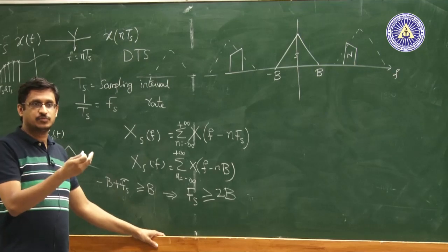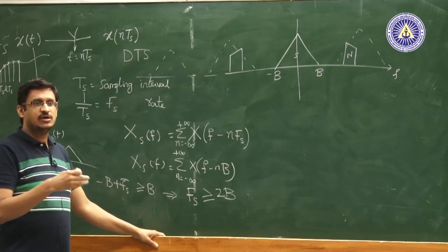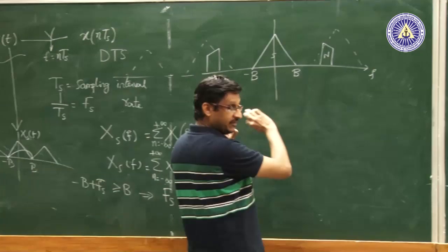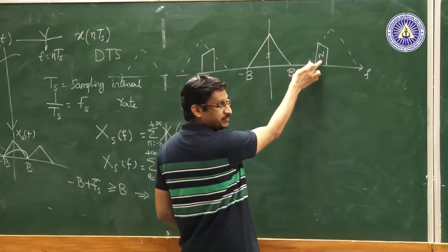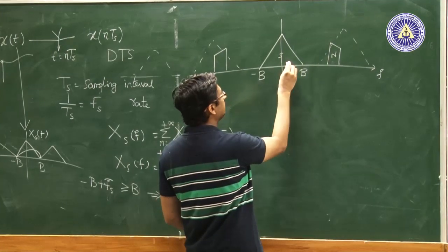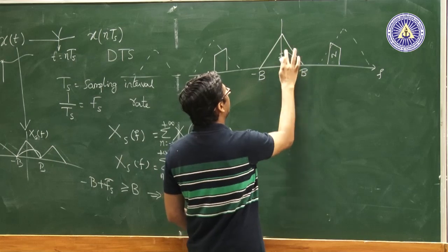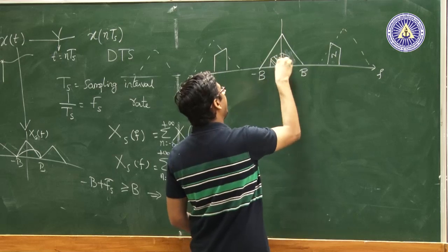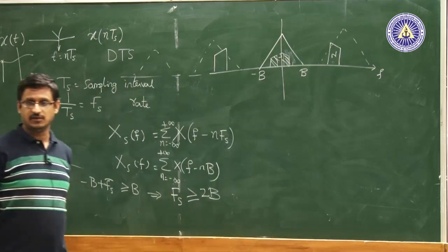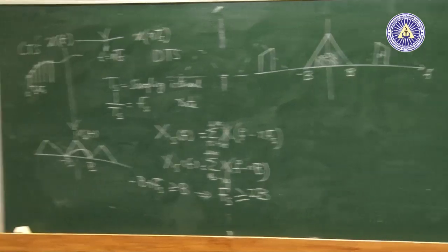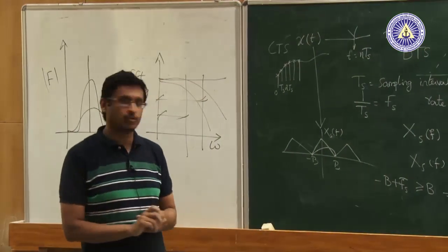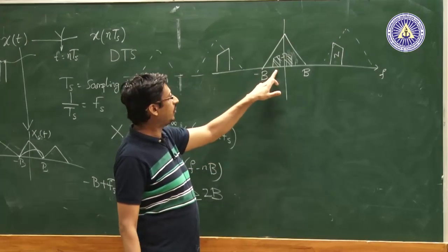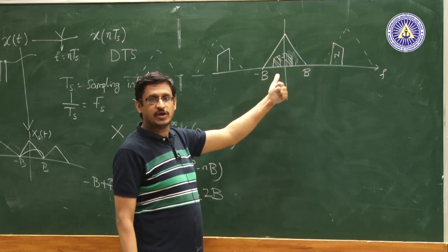because noise is also being sampled. You can't distinguish when you take a signal which also has noise in it, you can only isolate the signal and then sample it, right. You are sampling both. So, the effect of that in the frequency domain is that the noise spectrum also shifts, and this fellow will shift and usually will fall right into this one and then add noise into the signal band. If you had used a continuous time Fourier transform, you could have distinguished signal and noise. The sampled signal will have a Fourier transform in which, in the band of interest, you have the noise spectrum also.